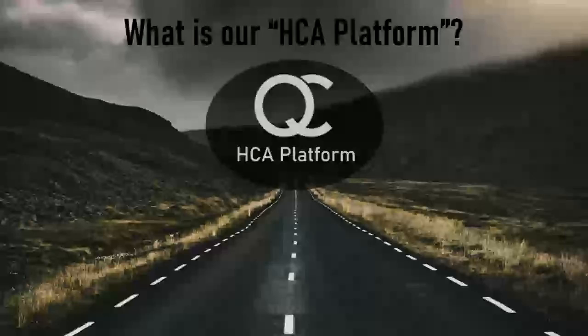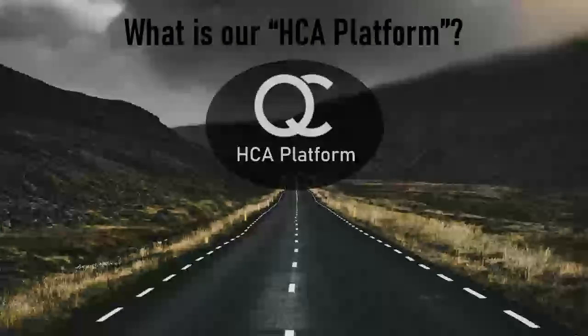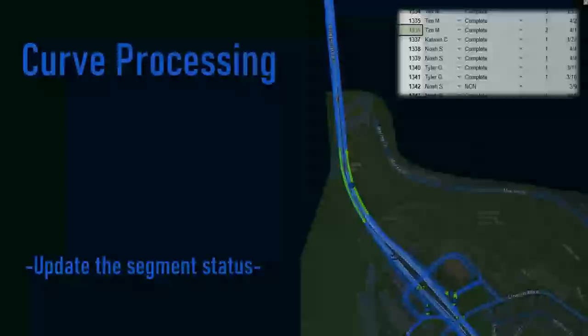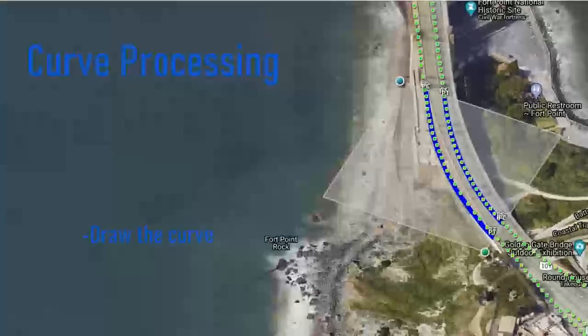That's the point at which the curve ends and the road becomes a tangent again. And in the software, where we process the curve data, there's a rectangle selection tool. Jay showed it on a previous slide. It allows the analyst to determine the PC and the PT and what data is included on the curve for a given location.